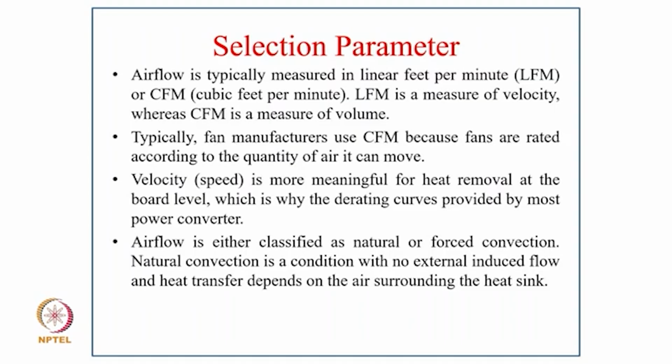And typically fan manufacturers use CFM because fans are rated according to the quantity of air they can move, and velocity is more meaningful for heat removal at the board level, which is why the derating curve is provided by most power converter manufacturers. Airflow is either classified as natural or forced convection.